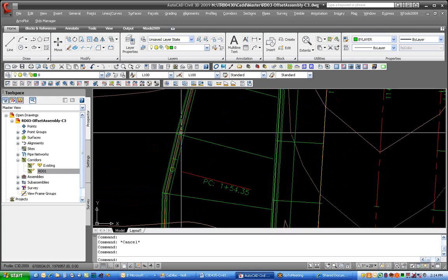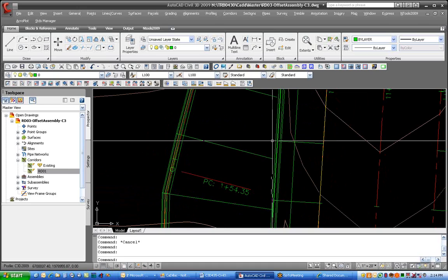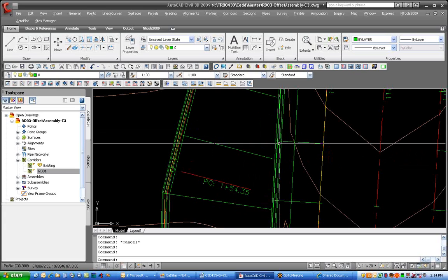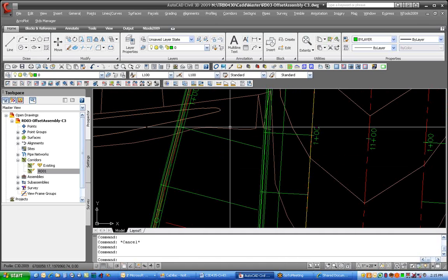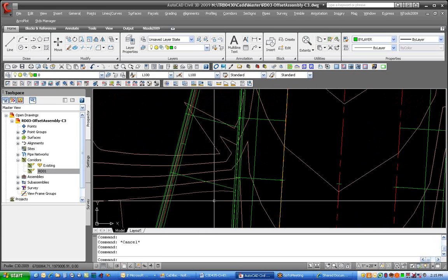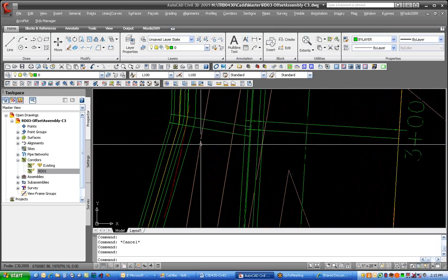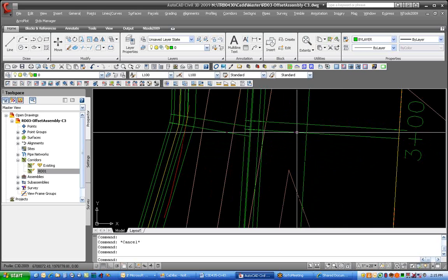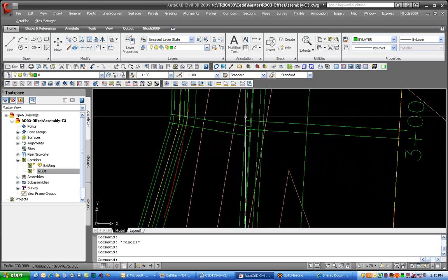You know, I probably need to increase my frequency. All right, but it's actually got that link that's going back from this point, and it calcs it relative to this point. The problem I have found is it's drawing it radially here, and they don't quite match up, and then we get some of those zigzag contours in here. Okay. The other problem with that is when I get to some of these areas, let me see if I can find one in here where I get closer. Here we go, like right in here. I've got a problem because these are not coming radial to my main alignment. They're actually intersecting the feature lines from my wall, and what's going to happen is I'm not going to get a very good surface model there.